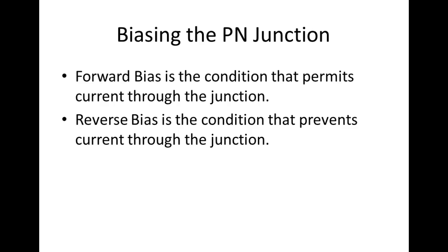If I close a switch across a DC source, we have a short circuit, and that is exactly what you would get with a diode. So we never put the DC source directly across the diode. You'll never hear me say make the cathode negative and the anode positive. I'll say that the cathode is going to be less positive than the anode, or the anode has to be less negative than the cathode, because it depends on what our common is.